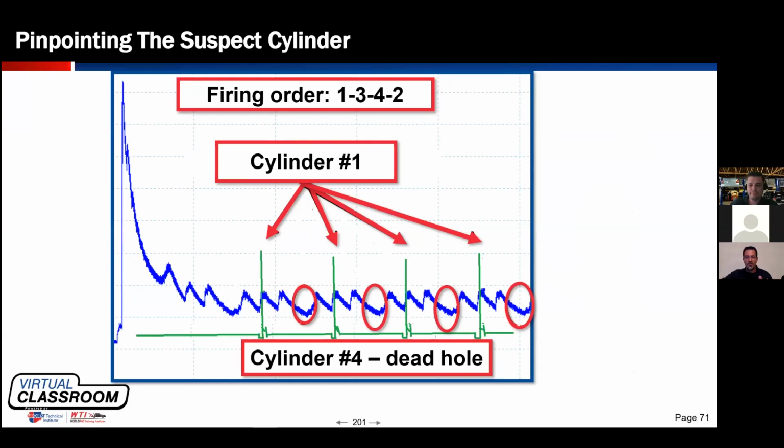However, if I did not do the relative compression test and I was kind of shooting from the hip, you guys see it all the time. Somebody does a compression test and then they do a fuel pressure test and then they go for another road test and they come back and then they want to move coils around and then they want to drop an exhaust system. And they're hoping to run into the problem. They really don't have a game plan. I used to do that when I was younger, before I established a game plan, and it wasn't fun.